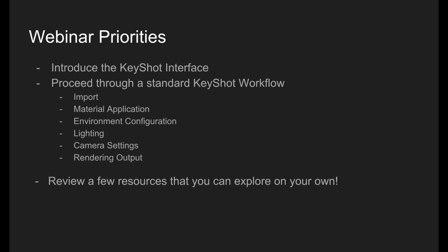Depending on what we are trying to render, there are different lighting settings, meaning that if we are creating a rendering of a product, we may want different ray bounce properties than if we are creating a rendering of an environment or interior design. KeyShot, as far as ray bounces goes, is a progressive rendering software and uses different algorithms based on the kind of display you would like.